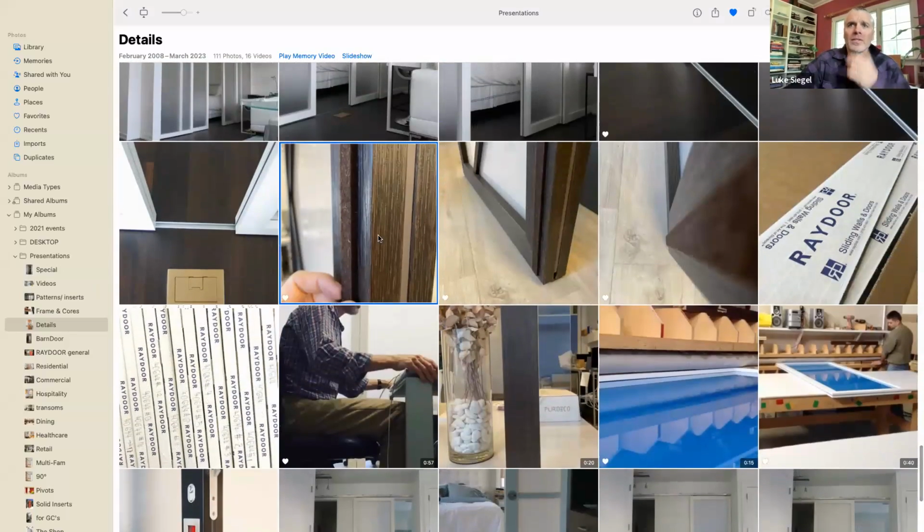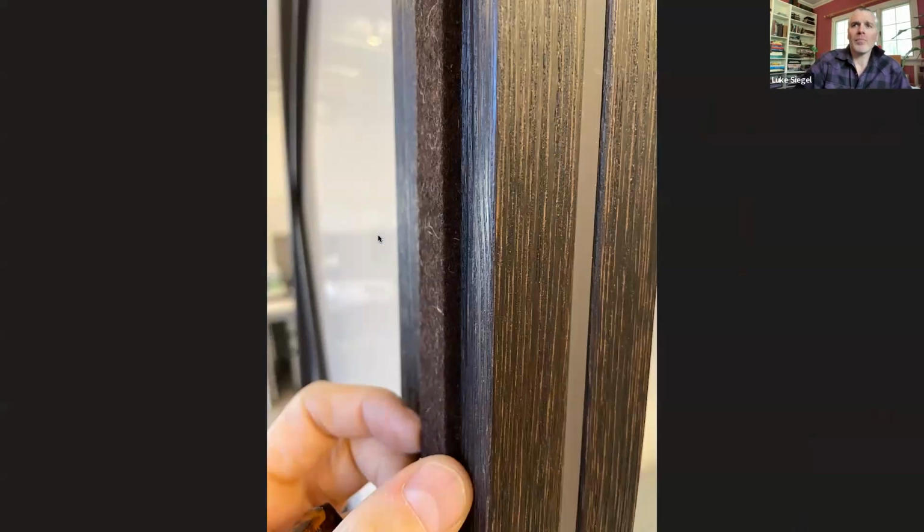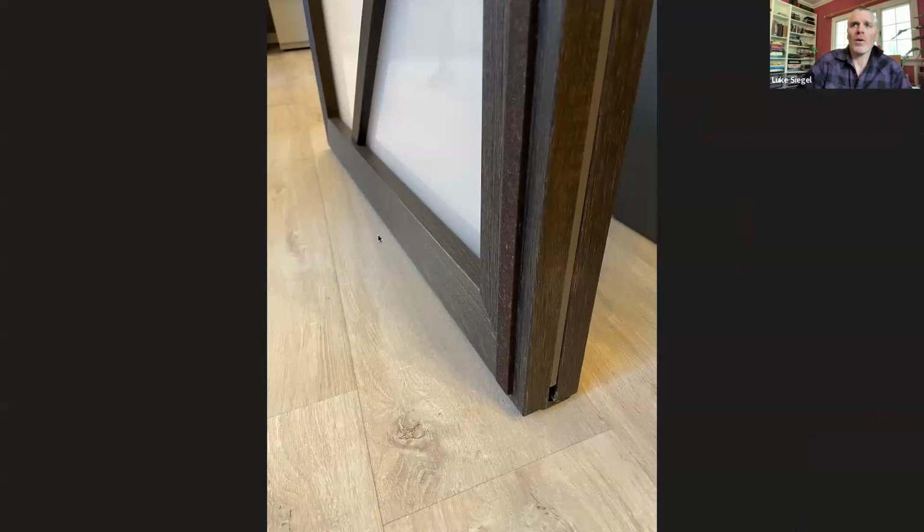Okay, here we go. So in the overlap of our bypassing systems and sliding walls, we have a felt that is mounted to the stiles, the vertical stiles, on each side. And it juts out in the gap, and they're offset. So when the panels come together and close off the space, two of these felt gaskets kiss in the overlap, and that is an enhancement that was done even after that demonstration that I showed you a moment ago.